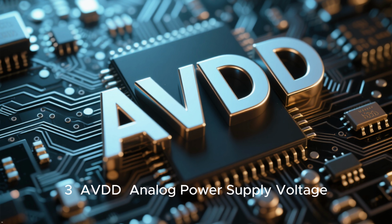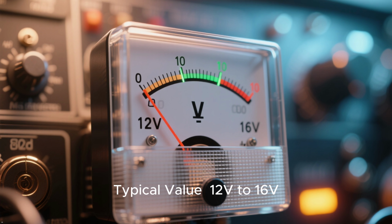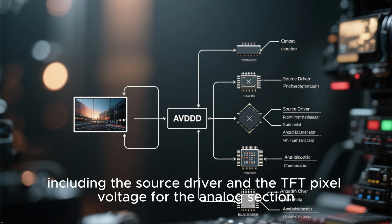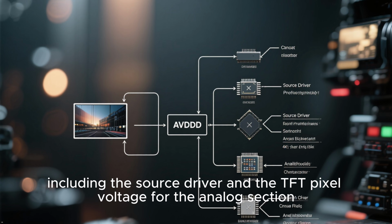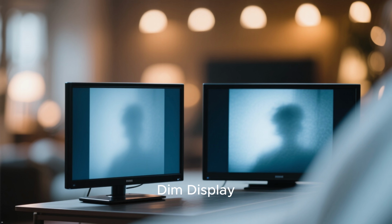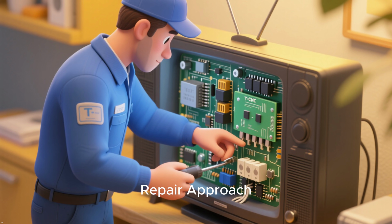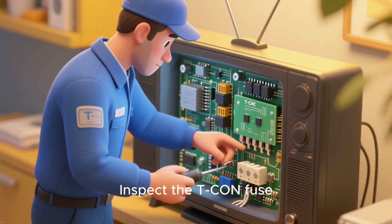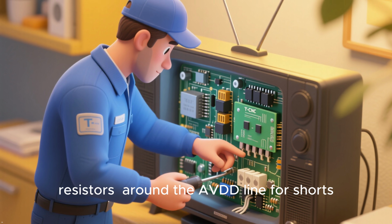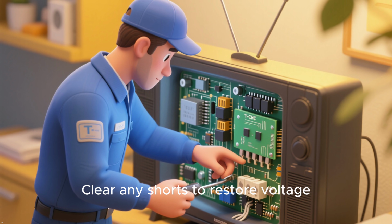3. AVDD, analog power supply. Voltage: typical value, 12 volts to 16 volts. Function: powers the analog circuitry, including the source driver and the TFT pixel voltage for the analog section. Symptoms: if missing, no picture, dim display, color distortion, washed out or inaccurate colors. Repair approach: inspect the TCON fuse, DC-to-DC section, and all components, capacitors, resistors around the AVDD line for shorts. Clear any shorts to restore voltage.